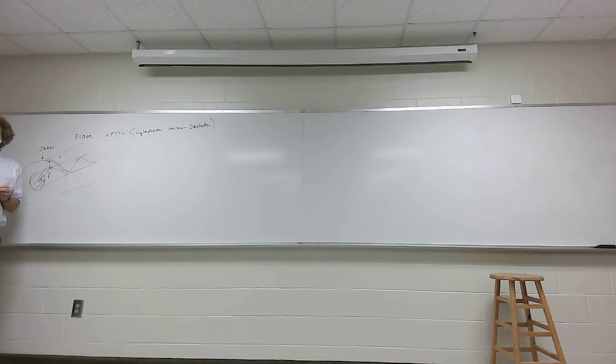I'm just giving you the basic perspective. You have to appreciate this for this solution to make sense the way he did it. So there will be a field here, but it dies off very quickly, and it's an evanescent field. What it means is no energy is going to propagate that way. Y'all hear me? It will not propagate radially outward. If it does, then all the energy will not go down the guide, all right? It won't.